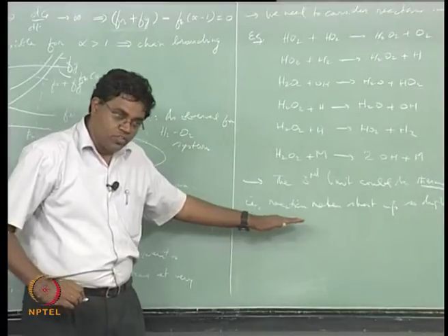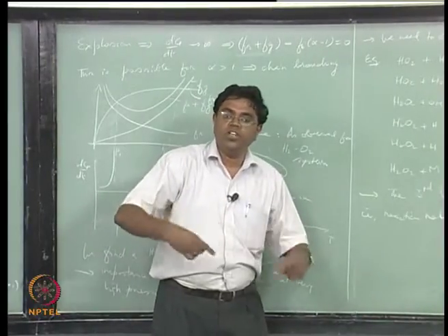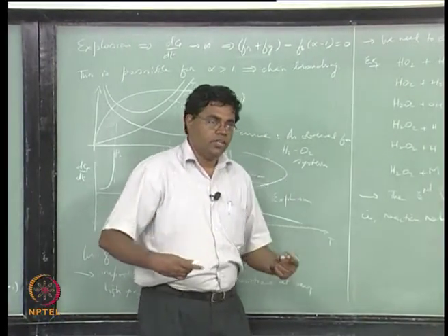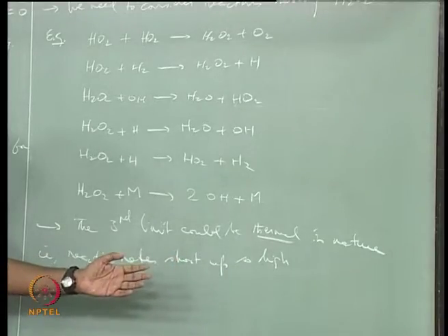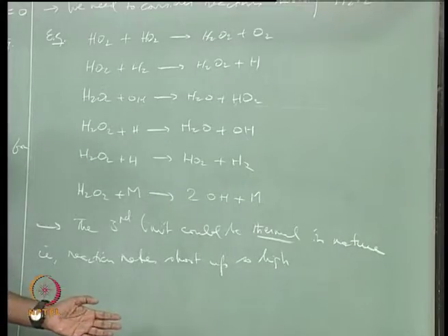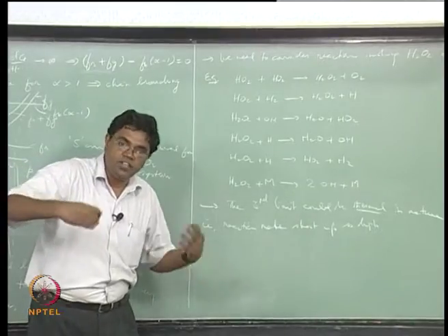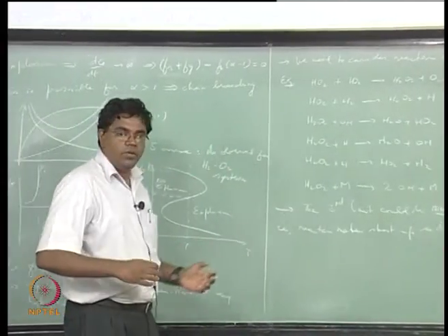So when you now have exothermic reactions that are happening very fast, right, then you have a huge rate of generation of heat, right, that could actually increase the temperature, and as the temperature increases the reaction rates increase further, right, and as the reaction rates increase further the heat release rate increases further as well, and so on, right. So that's what's called a thermal runaway.